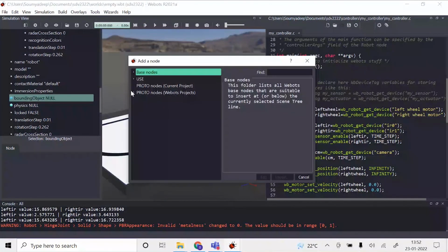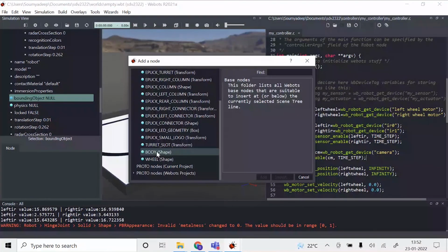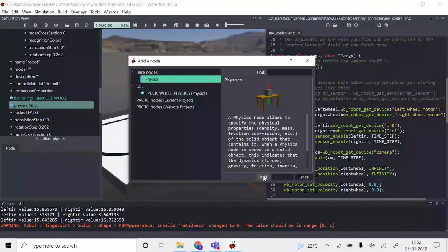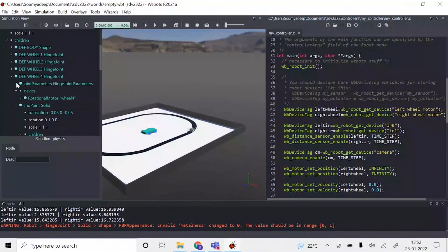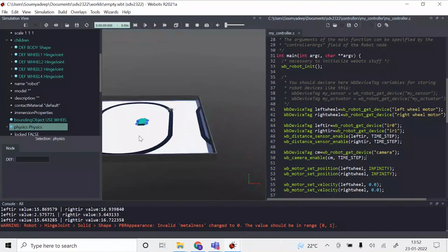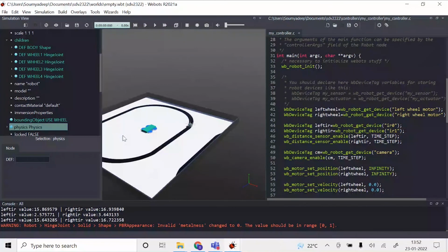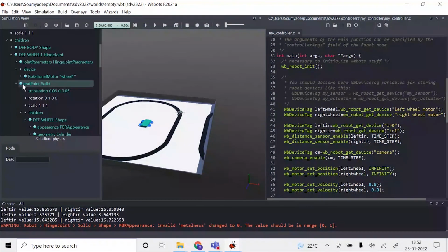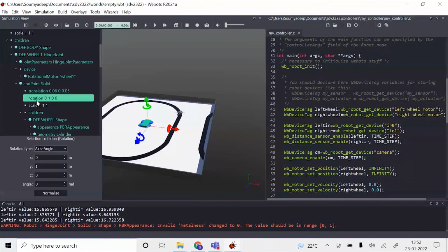Okay, as you can see here, the wheels are not flat to the surface. It has to be made perpendicular to the surface. So for that, I rotate the wheels along the z axis. Make it 0 and 1. Since you rotate it by 90 degrees, and the value of pi is 3.14, pi by 2 is 1.57.